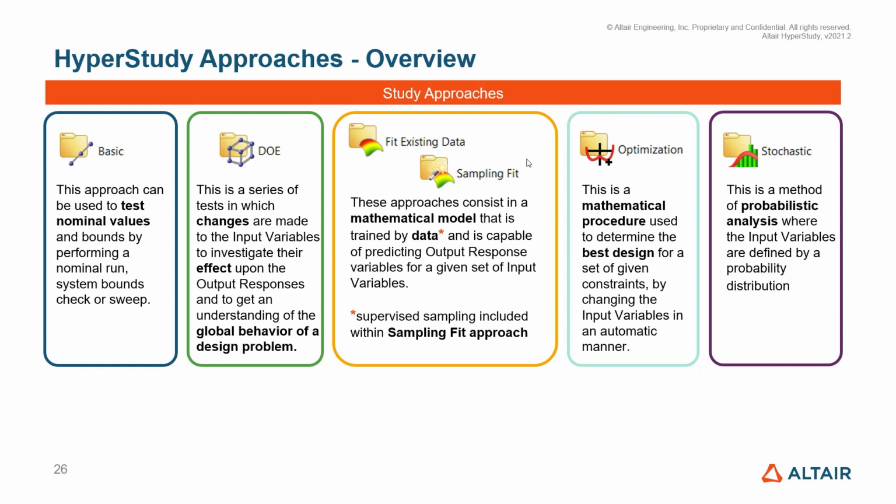these stochastic models. Rather than saying my input thickness is always 0.1, I start to account for the fact that I have certain tolerances when I manufacture things. Sometimes my thickness is 0.1, and sometimes it's 0.095, and sometimes it's 0.11. We start to look at this with a more realistic approach and consider the different values and the likelihood that our model is to take on these different values and how that affects our outcomes.